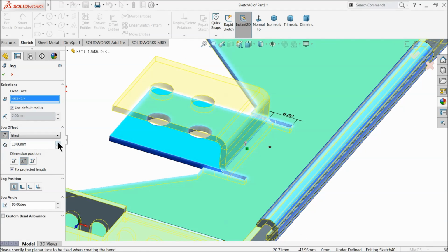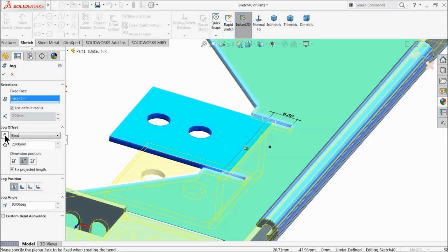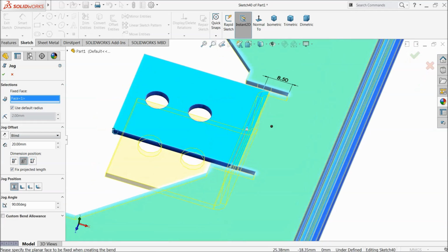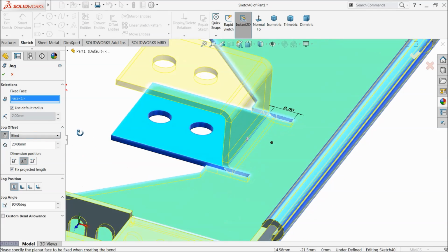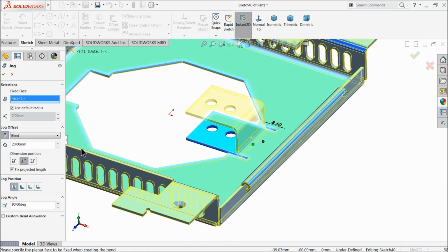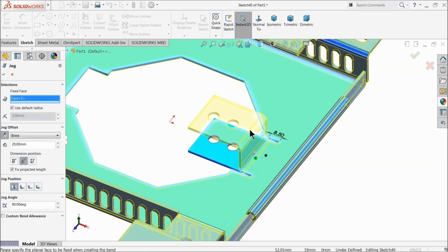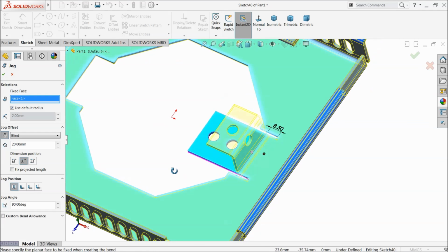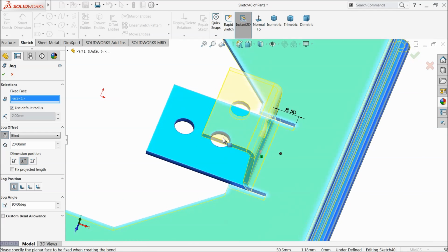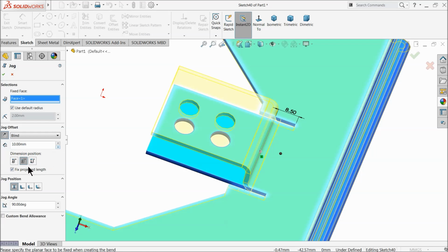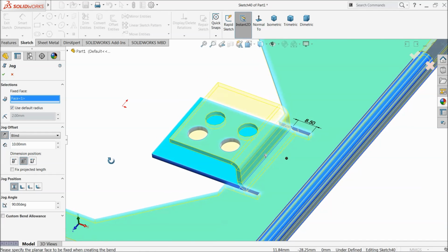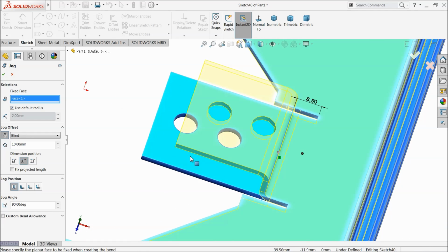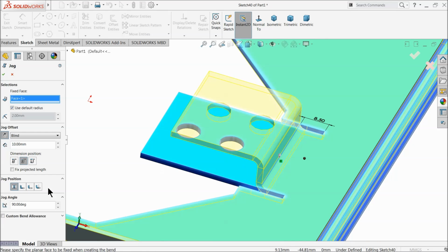See, here you can define the height, 20 millimeter. Reverse direction, now it is in bottom position. See, upward position. And this is the thickness what you want to define. Fixed projection length, if you uncheck it, see, it's going back and going to take this position. If you uncheck, just reduce this to 10 millimeter, then uncheck. That's it. Now see, after sync it would be like this. Angle you can change according to your requirement.